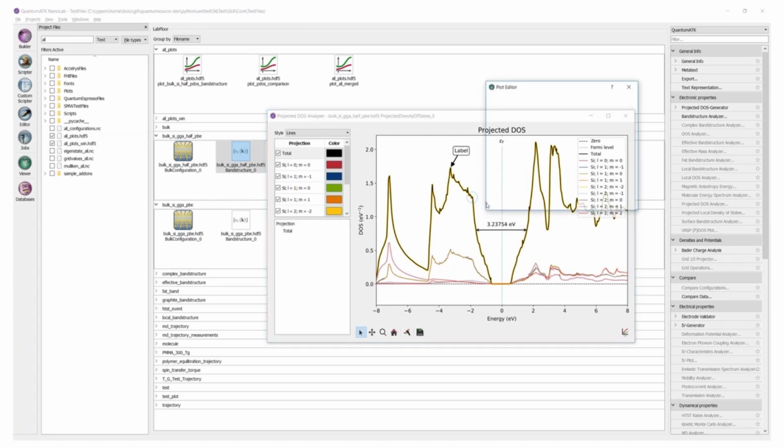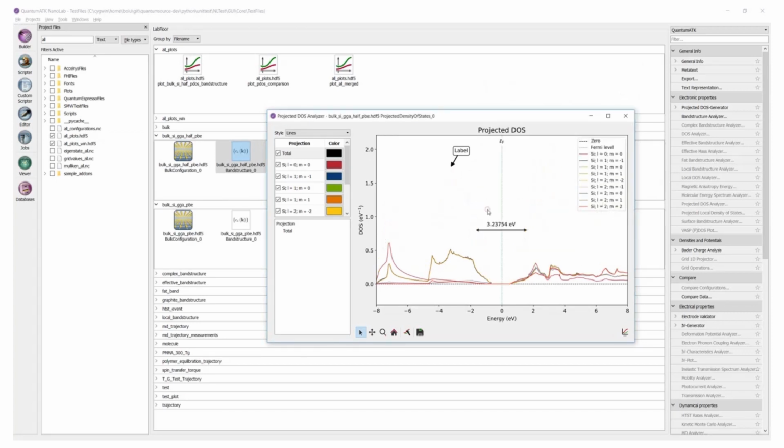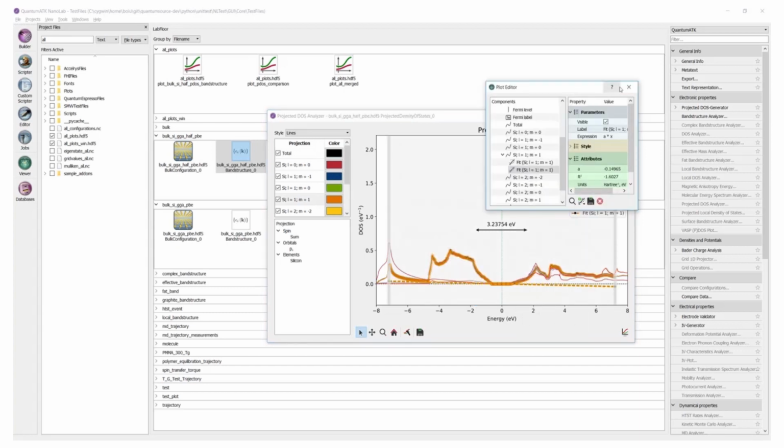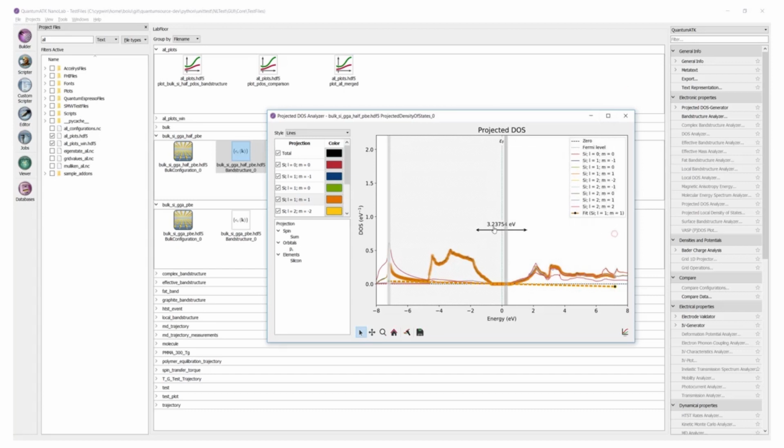Right-clicking on an item provides the additional options to open the plot editor or to hide the item. For non-data related items, there's also the option to delete them, while for data related items, there's the option to fit the selected data with a function. Similar to the annotations, fitting functions come with their own custom interactions in the form of two draggable lines to set the fitting range.